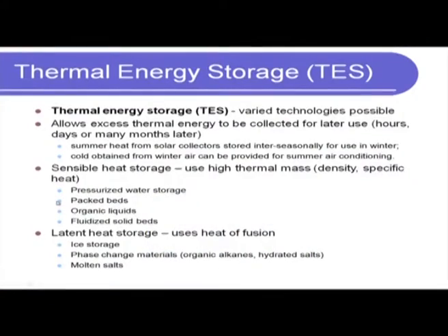So, this is one way of sensible thermal energy storage, which we have already seen. Packed beds is one. Organic liquids: again in a regenerative manner, a hot fluid exchanges heat with an organic liquid, and the liquid is chosen such that its thermal mass is high, and later the heat is released.